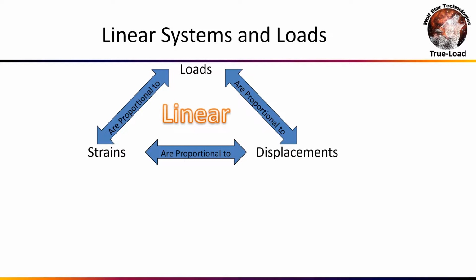So we're going to target the nominal regimes on the part. We're going to stay away from welds. We're going to stay away from bolted joints. We're going to stay away from areas of contact. We're going to be in nice nominal areas on the part where the strain response remains linear and proportional to the exterior loading. The loading can be as nonlinear as anything. The loading can be sinusoidal, ramp loading, impact loading. That's all okay. We just need that strain response to remain proportional to that exterior loading.